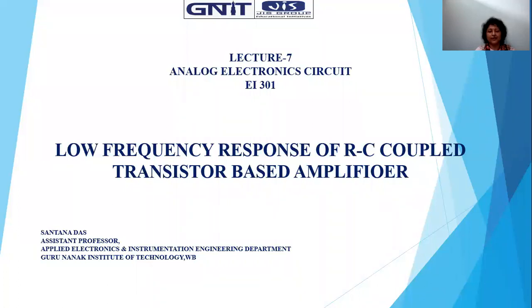Now we will analyze how the frequency, with respect to the lower range as well as the higher range, will affect the transistor gain. With respect to certain parameters involved in this network, that will mainly hamper the frequency response. In the low frequency zone, we have already analyzed in the previous class how the externally connected capacitors, CS, CE, CC, that is the biasing, coupling or bypass capacitors, will hamper the gain in the lower range of frequencies.